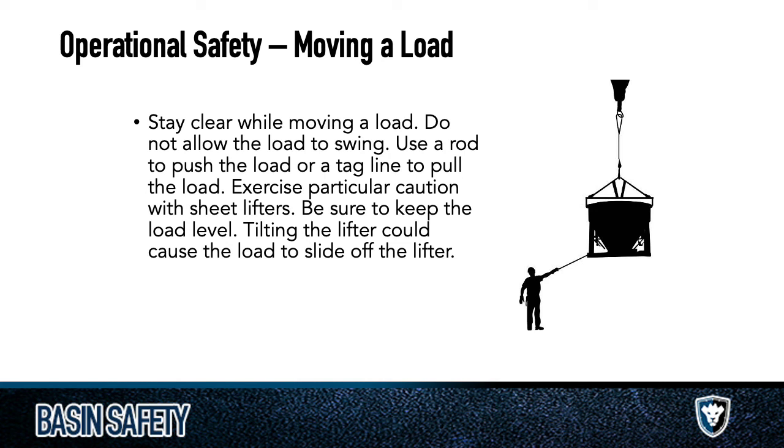You want to give yourself a little bit of distance so you have control without it potentially yanking you underneath the load. So, if you're walking with the thing, you want to have enough distance so that you have some play and you can step around things and have a little bit of rope. So just make sure your tag lines are long enough.